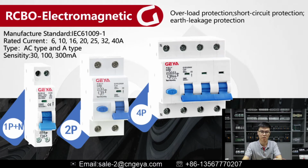You have these choices. And working type we can do is AC type and A type. And the sensitivity is 30 milliamperes, 100 milliamperes, and 300 milliamperes.